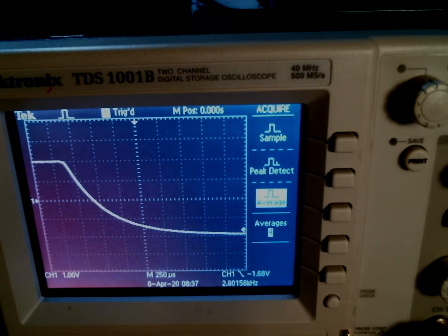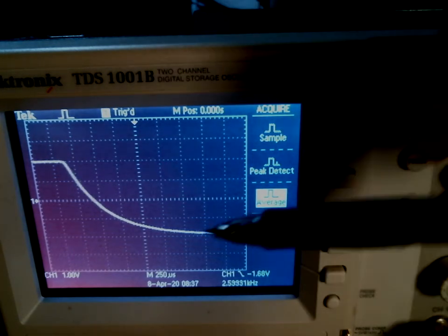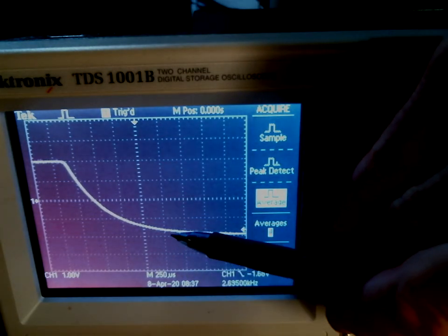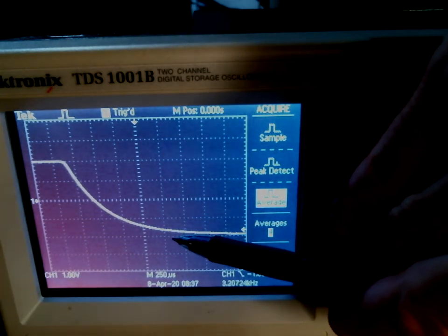If you look at the vertical scale, you can see that it's going from about +2 divisions to about -2 divisions, and that's because of the amplitude we set on the function generator. So because it's already centered on that scale, I think this line right here really is my baseline for the end of the exponential decay.